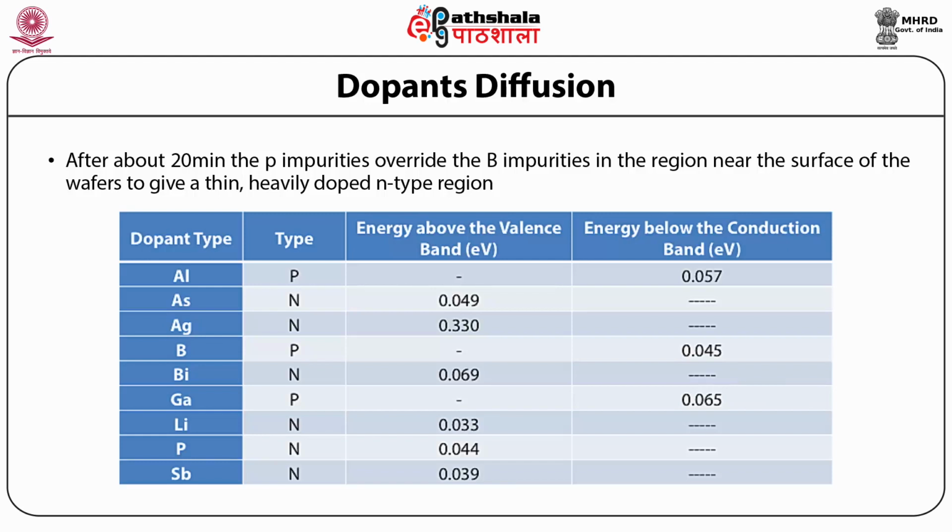However, this method has disadvantages. It is a batch process, it is costly, requires huge energy, and the diffusion occurs on both the sides of the crystal. So the uniformity is poor, and they have shallow junctions.